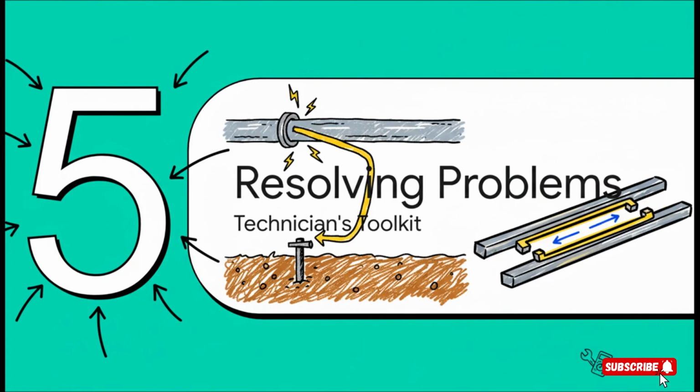Now what? Time to fix it. The goal is to provide that lost, stray current a safe, easy way to get back home, a way that isn't through our pipe wall. And the most common solution is an electrical bond.